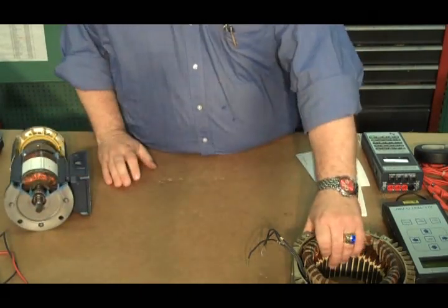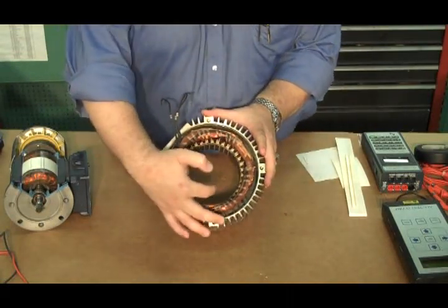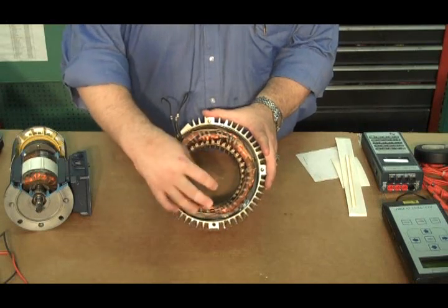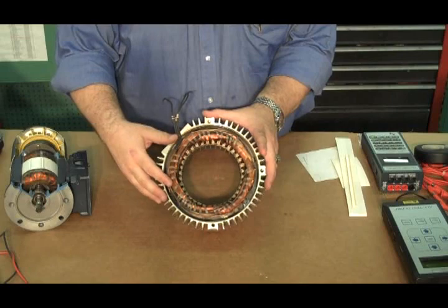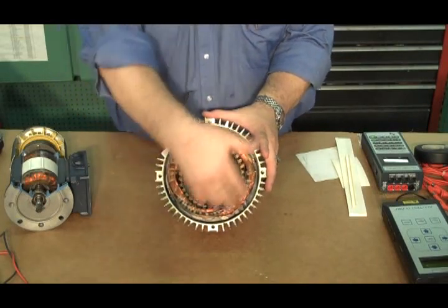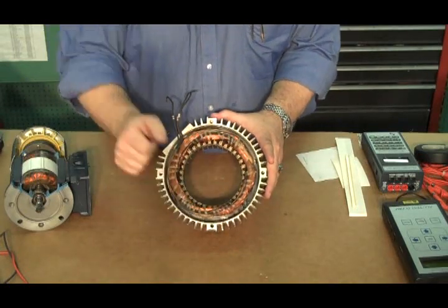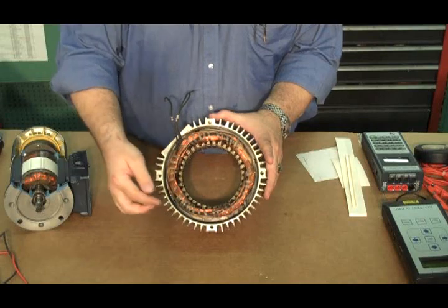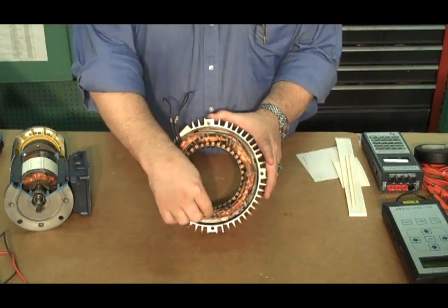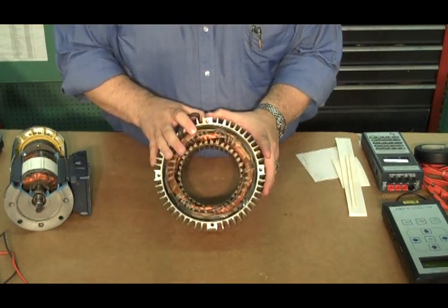So the winding itself looks like this. This is a concentric winding, which means I have an inner coil going from here to here, a middle coil, and an outer coil like this. The other type is called a lap winding, in which they're all evenly all the way around, like a cornucopia. This part of the system will have certain insulation components, which include the tying tape, which holds everything down, the enamel on the wire, and then your slot liners and slot sticks.